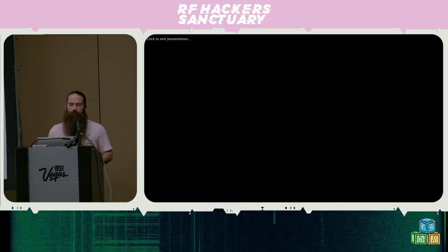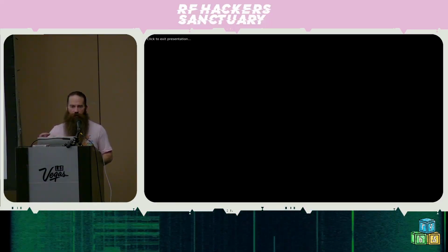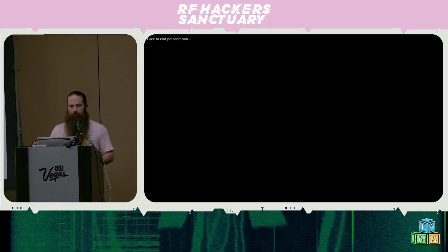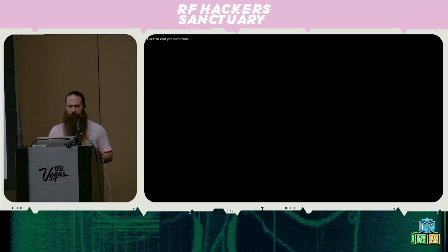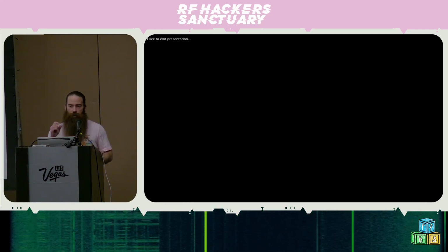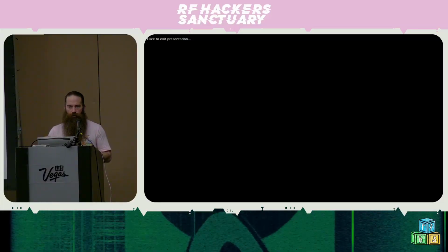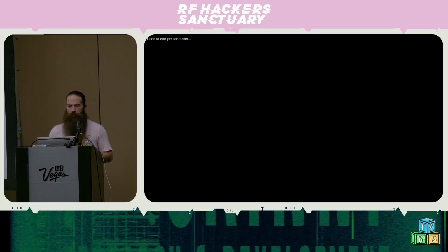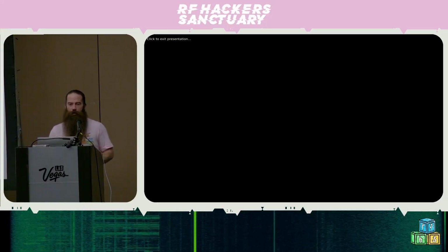So, the flow graph is essentially the same. Instead of a BladeRF or a HackRF or an Osmocom sink, we're using a ZMQ sink. And then the examples that we have, the RF CTF files or whatever it is, also on our GitHub, those flow graphs are just the ZMQ source into a file or into an audio sink or something like that. And those are examples just to get folks started. But yeah, that is essentially what's happening on the other side.